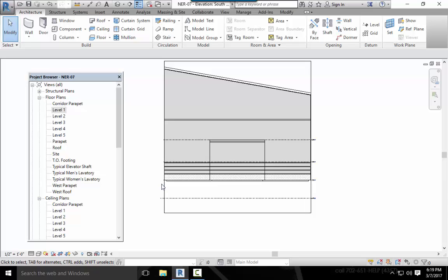The importance of the reference plane that you just added becomes obvious at this point. You need to establish a clear starting point for the roof you're about to add. Because the roof will be added in elevation, Revit doesn't know where to start the extrusion. This reference plane will serve as the starting point. Naming the reference plane is the way you can use them when they aren't visible in the view. Continue with these steps. On the Architecture tab, choose Roof, Roof by Extrusion.